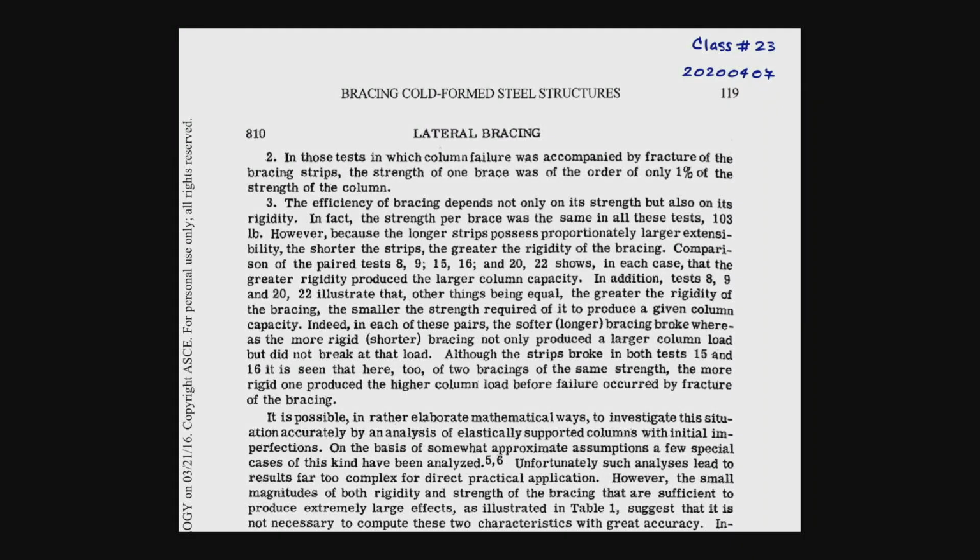Okay, so let's look into this conclusion from the test result. In those tests in which column failure was accompanied by fracture of the bracing strip, the strength of one brace was of the order of only around 1% of the strength of the column.